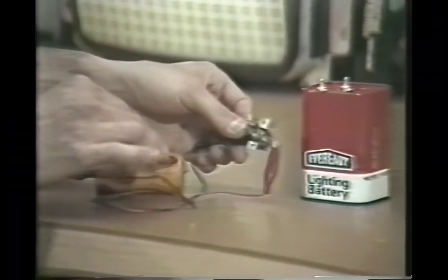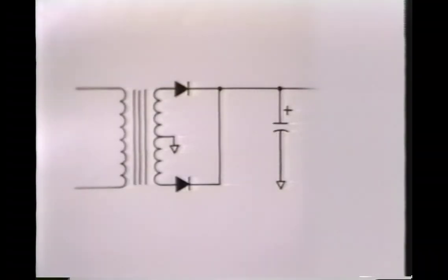Pretty neat, huh? Well, let's connect this capacitor to our full wave center tap power supply and see how it operates in a normal working circuit. The positive lead of the capacitor, which you can identify by the straight horizontal line and the positive sign, is connected to the positive output of the diodes. We know this is the positive output because the two cathodes are tied together. The negative lead of the capacitor is grounded.